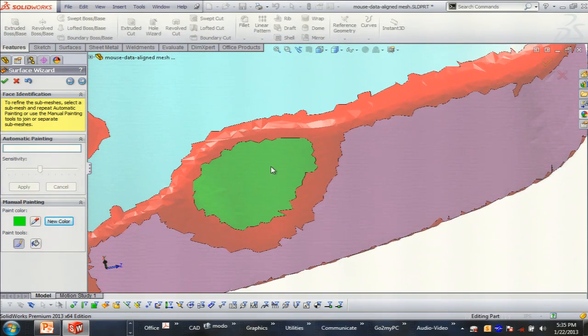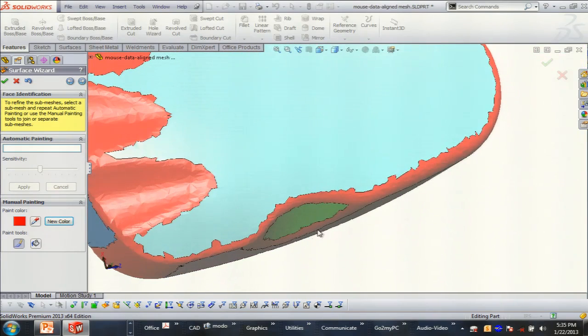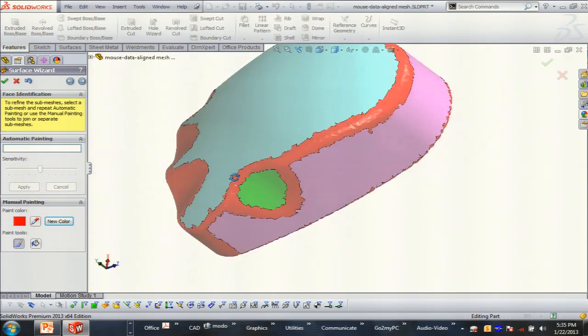And this is really important, guys, when you do this. Be careful not to extend the boundary of paint into areas that you want the guided surface to try to interpret. Like right here, that's part of that radius. I'm going to apply this as a radius later on. So I'm not going to let that be part of the solution, per se. I'm going to actually bring it really inboard. So I get just that kind of toroidal surface in there and do that.